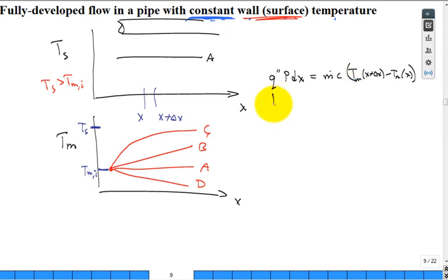For this, what equation do we use? We use the convection rate equation, which says that's equal to H times Ts minus Tm. True? That look good? Now, we can work with Tm. A lot of times it's better to just put in theta. What's theta? Ts minus Tm. Why do you want to put in theta? Well, because theta is a little easier to work with.